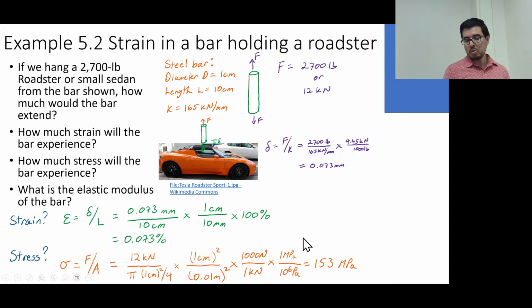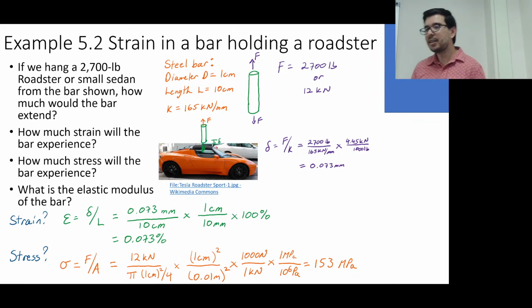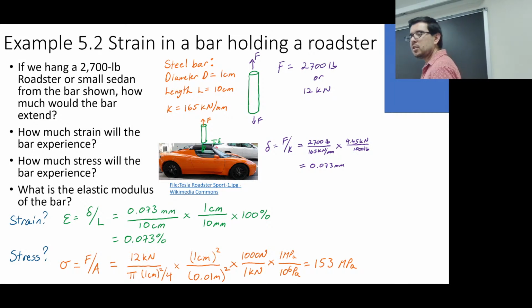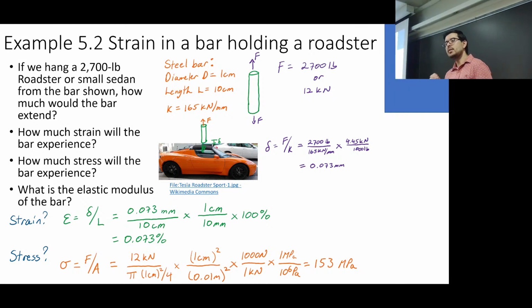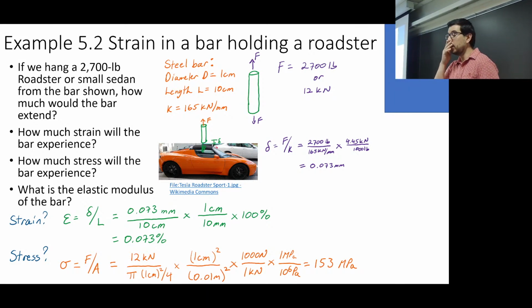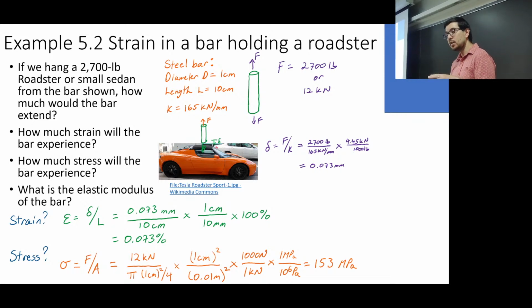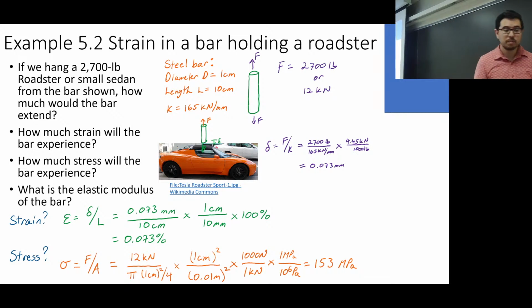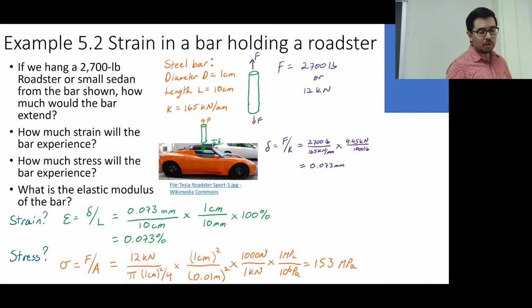We can calculate the stress. Stress doesn't care how long it is. Remember, we said the strength doesn't really care how long the sample is. How much it deflects cares about how long it is, but the stress or the strength of the material does not. And so here we can calculate the stress.